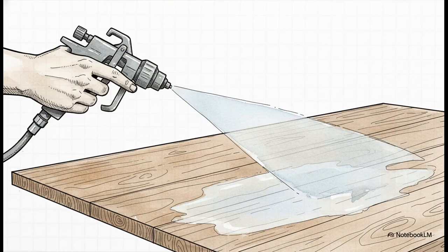If you need to cover a larger area fast, you can use the spraying method, spraying the liquid directly onto the wood's surface. It's definitely quicker than brushing, but just keep in mind, it generally gives you that exact same shallow, surface-level barrier. The deep core of the timber stays totally vulnerable.